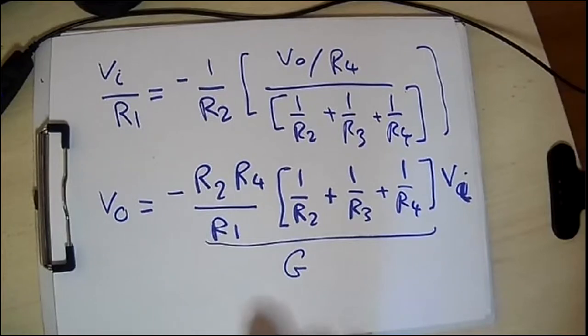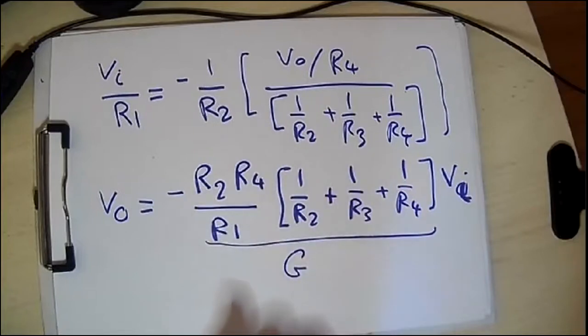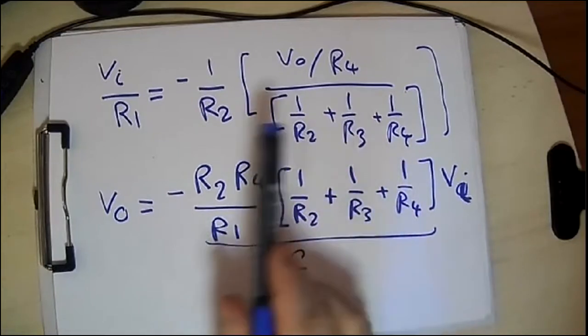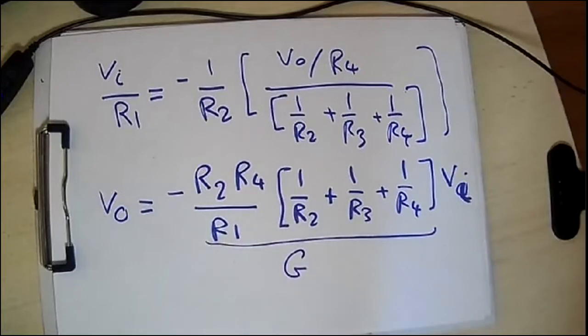Additionally, I invite you, my dear students, as one of our first bonus questions, to access these 2 configurations using Multisim and to examine the closed loop gain with the same values for the 2 configurations, and see how you can control the gain in this configuration and how you can control the gain in the previous configuration where you have only R1 and R2. This is actually very interesting for you.